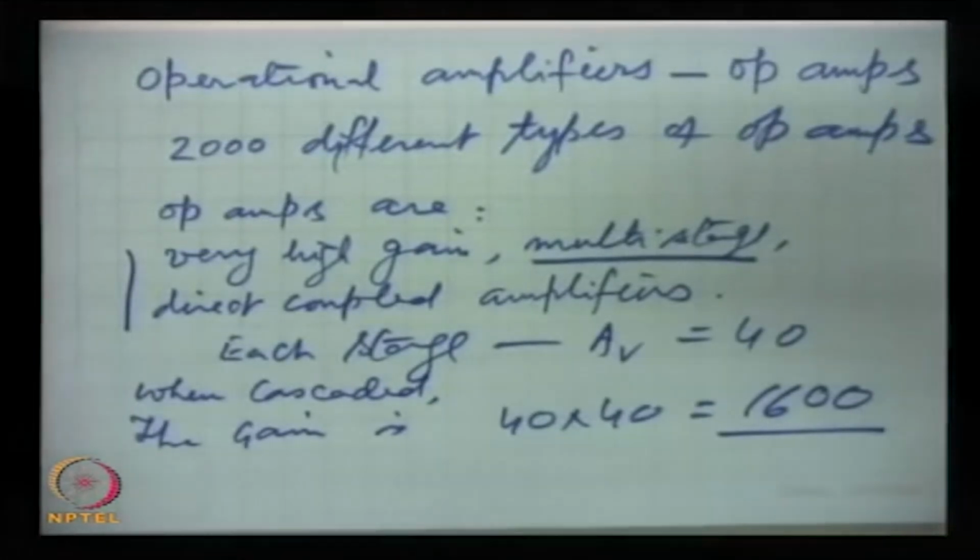Now, a word about coupling, for the sake of revival of the concept: what is the implication of this direct coupling? I said in the differential amplifier that we can use sinusoidal signals or even DC voltages as input signals. This is possible only with direct coupling.